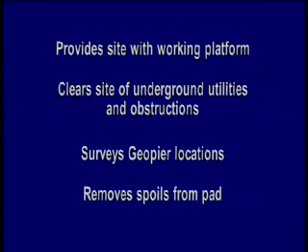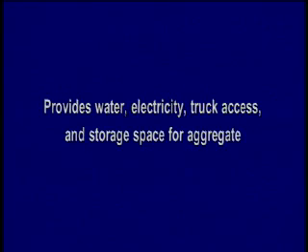Remove spoils from the pad. The Geopier installer will consolidate spoils on the pad, but the general contractor will remove spoil from the pad or reuse them on the site. Other general contractor responsibilities include providing a source of potable water for possible use for the Geopier installer to add moisture to the aggregate, providing electricity, providing truck and trailer access, and providing sufficient storage space to store enough aggregate for 4 days' work.